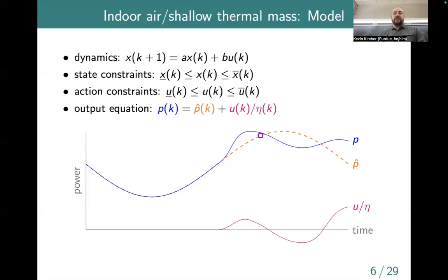Okay, Jennifer? You're trying to, instead of using the peak energy during like 4 p.m. on peak load, kind of shift the load a little earlier. Right. Preheat the building a little bit harder than they would when they have a lower demand. That way they can ride on that thermal capacitance throughout the peak. Yeah, so I would say that those are both right answers. The one that I had in mind is the second answer, that this would be a deliberately controlled thing.